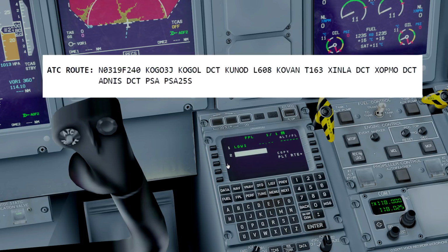So the first waypoint on our flight plan is the Kogel waypoint. So we'll just enter that right here, Kogel. Intersection, again some information, we'll just accept that value. We'll be entering an SID later on. So then you want to enter the next waypoint. In this case, the next waypoint is a direct, so we're just going to enter the next waypoint up here, Q0. Alright, hit enter, again some information so you can verify you have the right waypoint. That's correct. As you can see right now in the flight plan, we have a next waypoint via an airway.